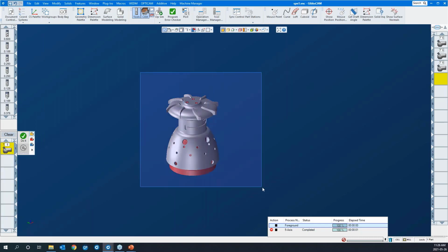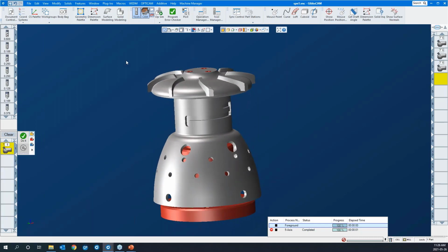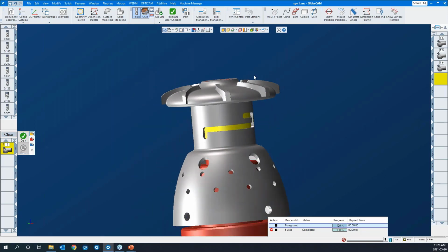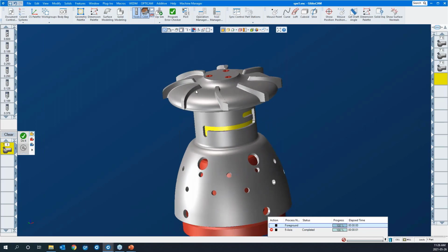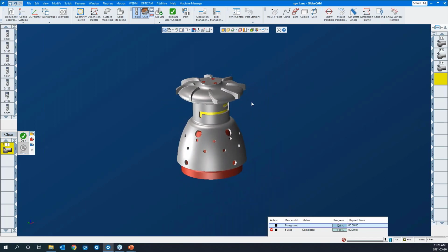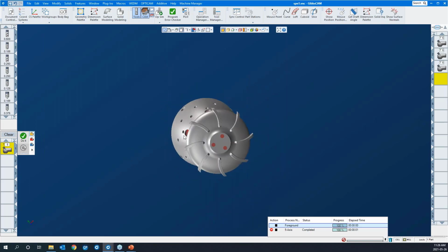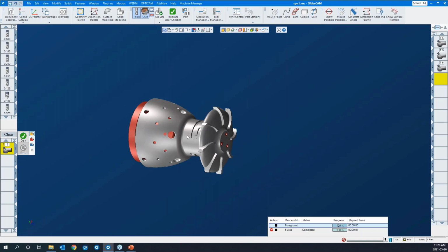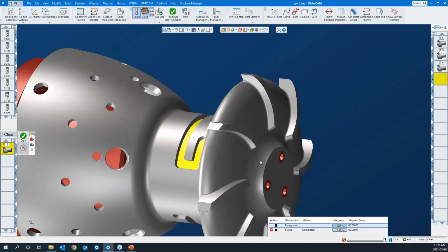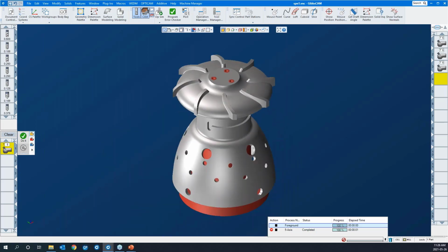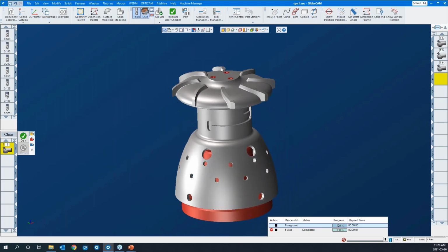So we're going to use those, and it'll just speed up our toolpath creation. We're going to look at this radial slot here. This is a 5-axis machine, has full 5-axis on it. However, if we were to rotate the part along the trunnion axis 90 degrees and access this slot, in a sense, we're now on a 4-axis mill. Although this is 5-axis, this certainly can be done on your 5-axis or your 4-axis vertical mill or horizontal for that matter.